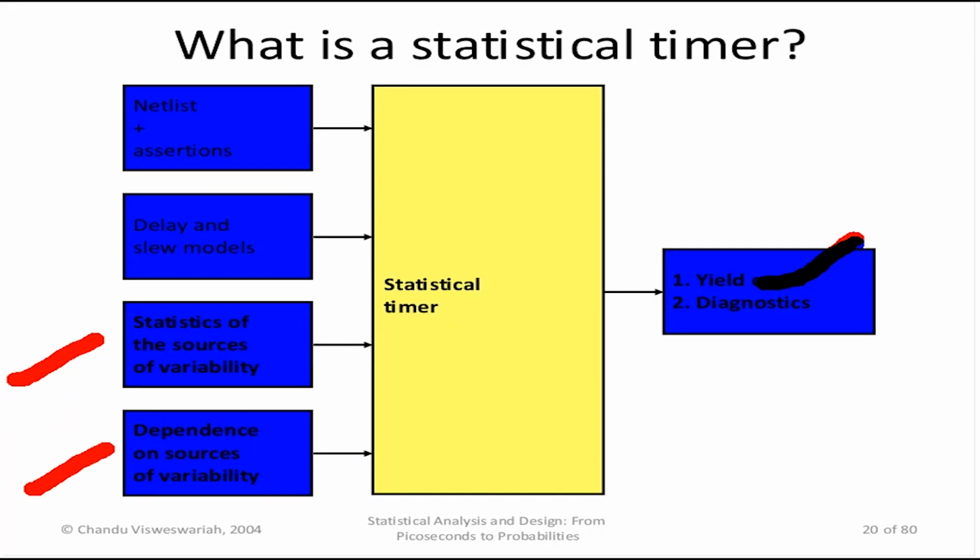A lot of testing would be involved, and apart from giving the slack, it actually gives the yield directly. It tells us that with this particular timing violation, this is your yield, right? So it tells us that. Obviously, the path that is shown to us as violated will probably not violate at a typical corner. Even if we don't solve some timing violation, we will have some amount of yield, although it will be lower. So this will give us the yield number also.